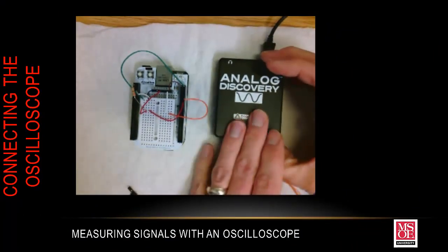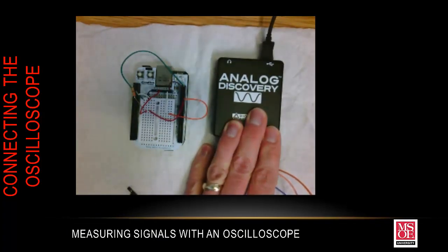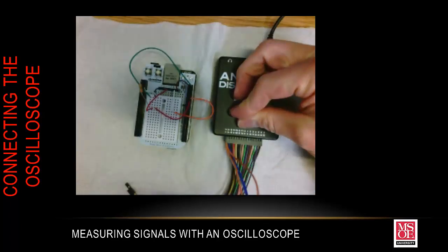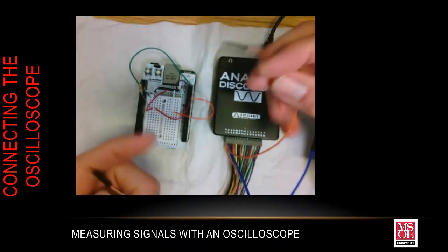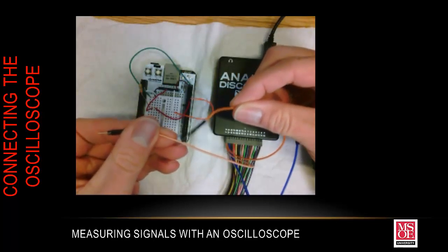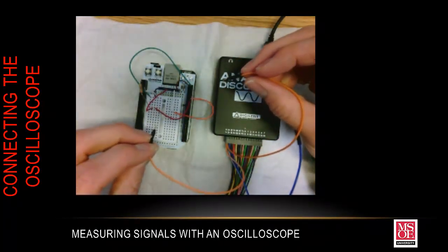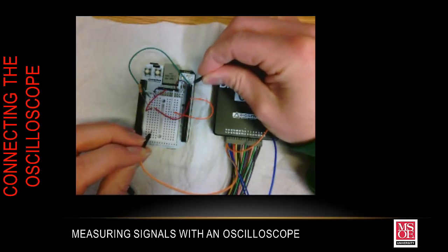Here is our Analog Discovery board all set up and plugged into my laptop via USB cable. What I want to do now is connect it up to the system. I have here channel 1, which are these two leads. I'm going to connect these up so that they are on the switch. One of these lines is orange with a white line on it. That's going to be our negative voltage, our ground voltage, so I want to connect that to a point that is grounded. The ground connections are these top two connections on the Beaglebone, as we've talked about in class.